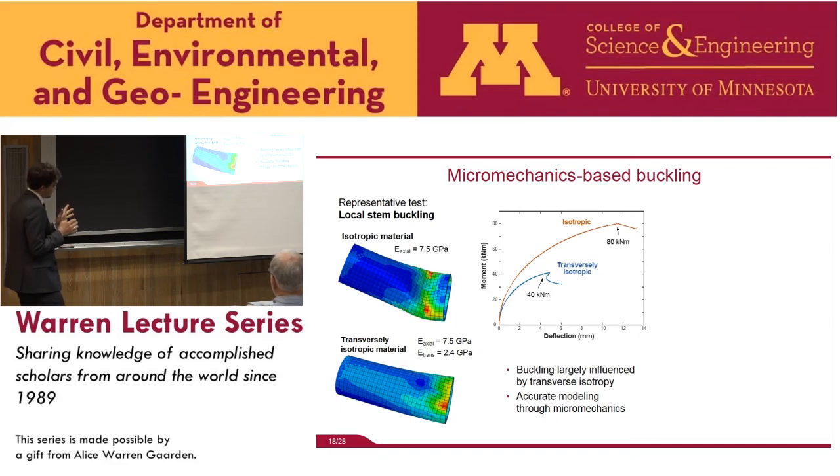The problem is now, of course, that these transversely isotropic properties are extremely hard to measure experimentally, because testing along the stock is possible, but testing in the transverse direction is hardly possible. But with this micromechanics-based model, we can automatically build up accurate material coefficients